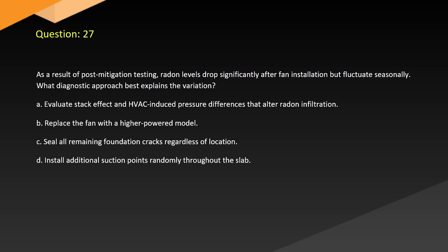Question 27. As a result of post-mitigation testing, radon levels drop significantly after fan installation but fluctuate seasonally. What diagnostic approach best explains the variation? A. Evaluate stack effect and HVAC-induced pressure differences that alter radon infiltration. B. Replace the fan with a higher powered model. C. Seal all remaining foundation cracks regardless of location. D. Install additional suction points randomly throughout the slab.